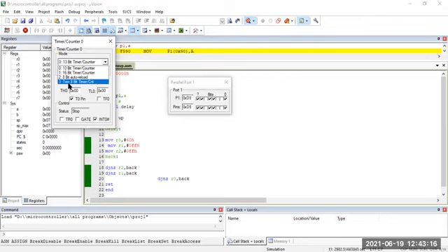Two 8-bit counters means separately we are going to use TL and separately we are going to use TH. For counting 00 to FFH in the TL, 00 to FFH in the TH, you have to observe the values here. You can execute the timer programs. It is not there in the lab. Actually, in the lab, you have C programming of the timers, so I'll teach the C programming of the timers. Only assembly language programming is there for counters, that's why I'm teaching it for counters. You can observe here, once it has reached FF, it starts counting again from 00. This is the 0th bit and this is the 7th bit.